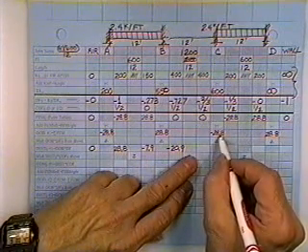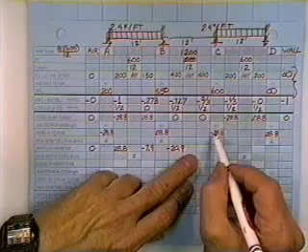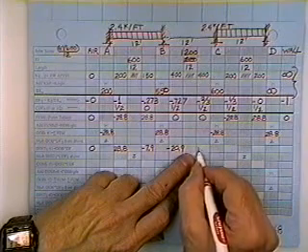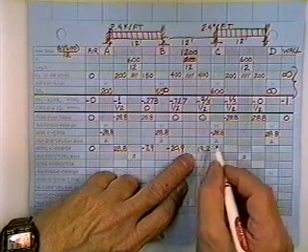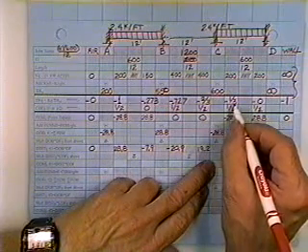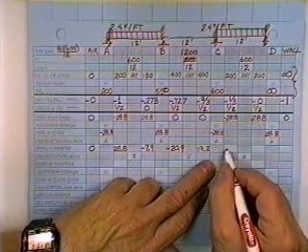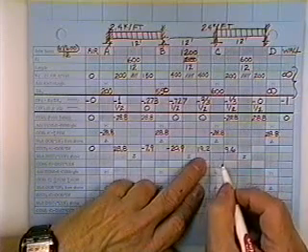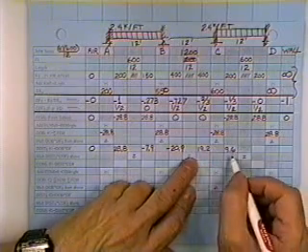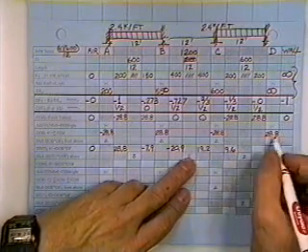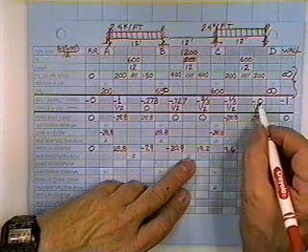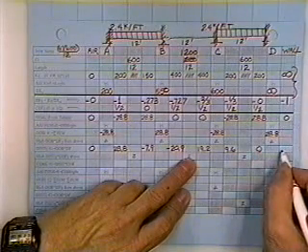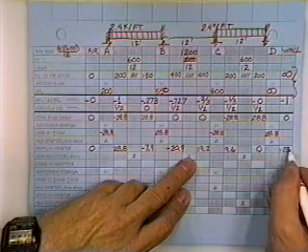Next, 28.8 times the distribution factor of minus 2/3. A minus times a minus is a plus. So it's 19.2. Thank you. And 28.8 times a minus 1/3 is a positive 9.6. Let me see right quick. 6 and 2 is 8. 9 is 18. That's right. And add a 1. That's correct. That adds up to the original 28.8. 28.8 times none is none. 28.8 times a minus 1 is a minus 28.8.